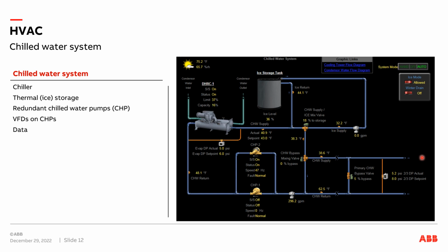So what do I mean by going out into my system? Well, it's going out to all my air handlers. I've got these 7 different air handlers throughout my building that all need chilled water in order to cool the air coming in from outside, or the return air that needs to get cooled down. So that chilled water goes out to the air handlers that we talked about, and then picks up some heat and comes back. And you can see a pretty big delta T here, from 38 degrees to 62 degrees. And that chilled water comes here.